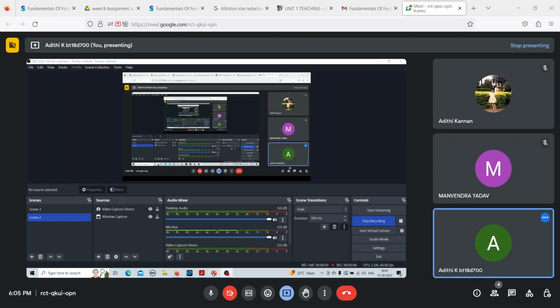So 2C is equal to 0.3162 into Wi, which is root 0.1, equal to 0.3162 into Wi, and I'm substituting it back inside the Bond's law equation. So instead of 2C, I'm substituting 0.3162 into Wi into 1 by root of Xp minus 1 by root of Xf, and that is equal to your power by mass flow rate. We have Wi given in the question. We know the size of the feed, we know the size of the product, we know the mass flow rate, from where we can calculate the power.